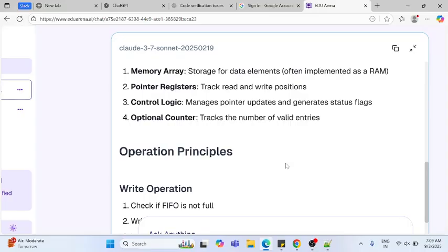You don't have any address lines in this. There is no address line because random reading and writing is not possible in the case of FIFO. Its purpose is not like that. For random reading and writing, you can use either static RAM or DRAM. But as FIFO is being used as an internal interconnect component, it is important for us to utilize the FIFO effectively whenever a queue kind of operation is required to be performed.